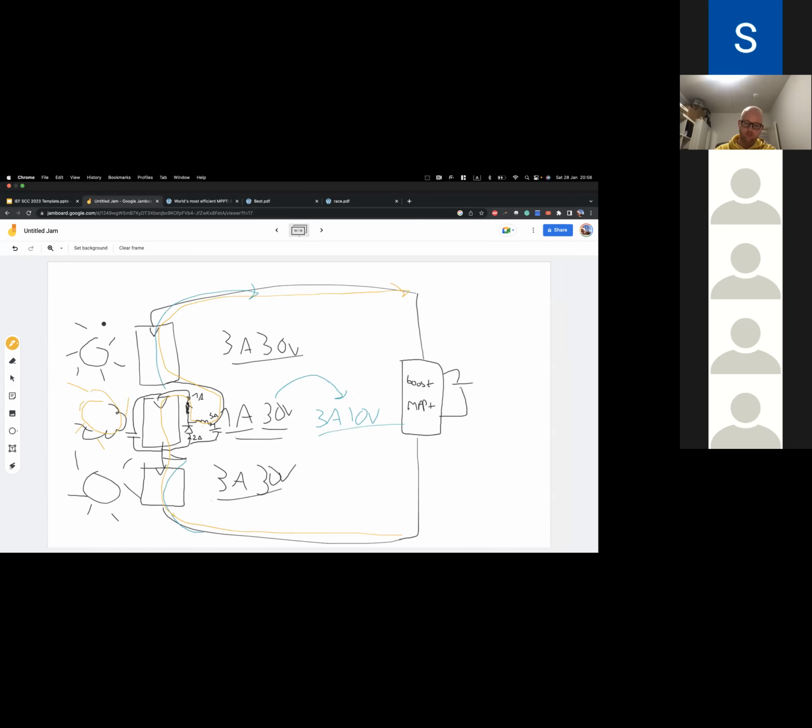So Elmar, if you don't mind, in summary with what you've just shown there, you're basically saying that instead of a bypass diode, even an ideal bypass diode, you would suggest possibly looking into a boost, buck-boost converter on a group of cells. A buck, basically what I'm drawing, the extra thing I'm drawing here, is a buck converter. Yeah, sorry, a buck converter from 30 volt nominally to 10 volt. Got it. Okay. Let's call it a buck optimizer or something, like a solar optimizer.